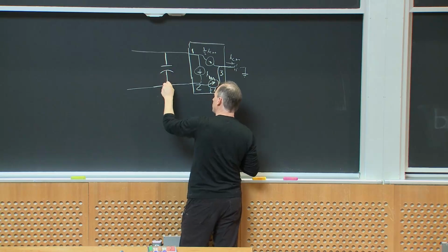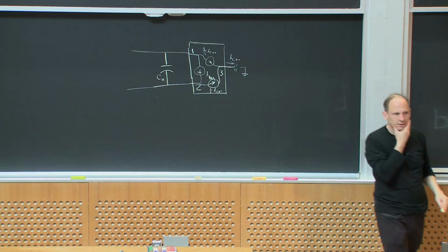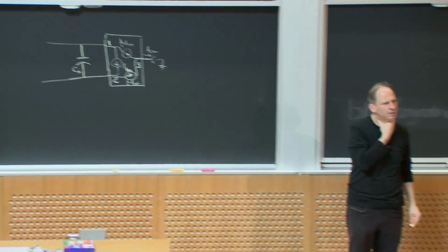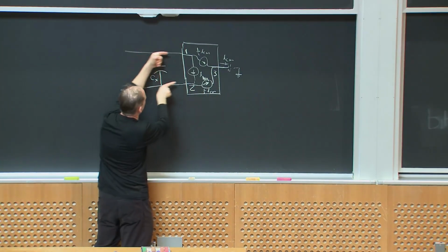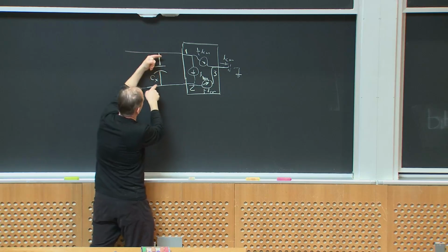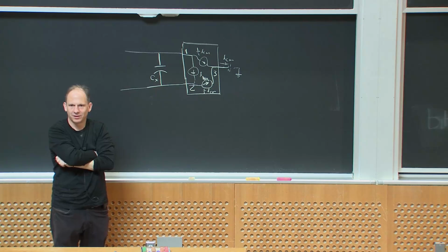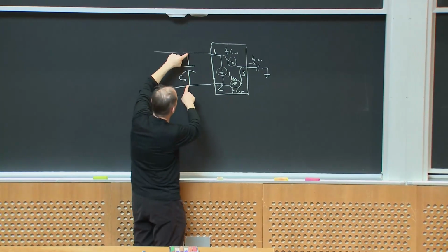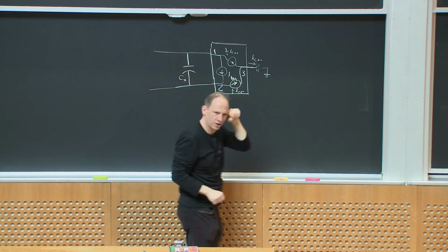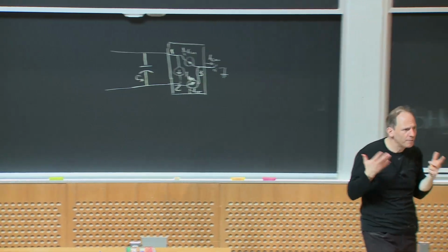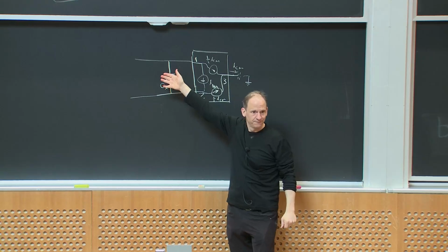And I'm going to call this, for reasons we'll discuss, C sub x. Okay? Does this capacitor really do anything? If the currents are equally coming this way, this capacitor is sort of like an open circuit to those currents. Or if V1 and V2, the voltages, are going up and down together, it has a common mode component to the voltages, C sub x is drawing no current. So for the common mode case, C sub x might as well not be there.